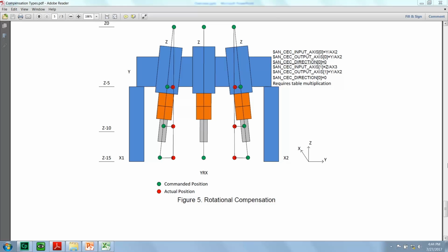It can be somewhat expanded to have a single rotary axis. If this is the case that you have, and you have a 5-axis machine, whether it be a tilt-rotate head, tilt-rotate table, or some kind of mixed combination of the two, that's a point where volumetric compensation, sometimes called VCS, needs to be investigated. Using just the sag tables, some improvements can be made. It can make the machine better, but it is not as capable as VCS.